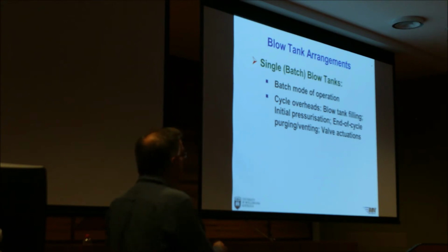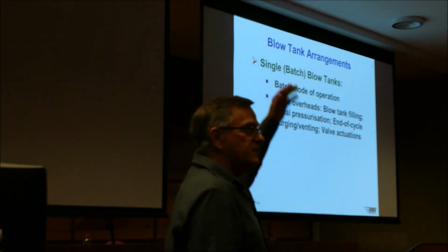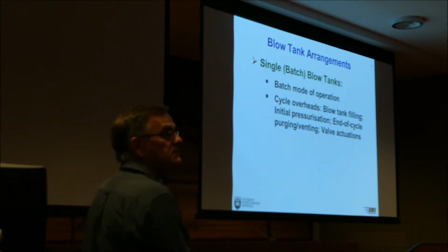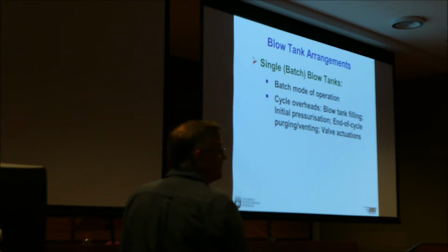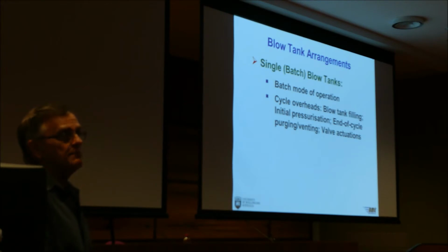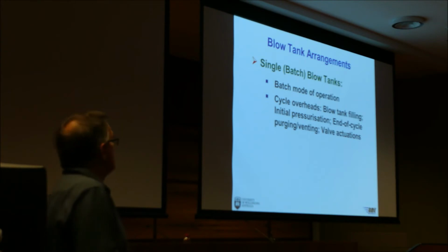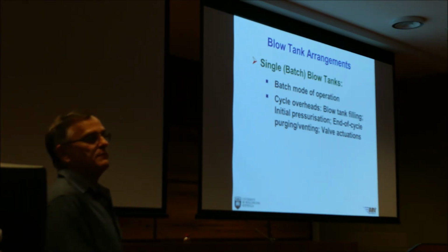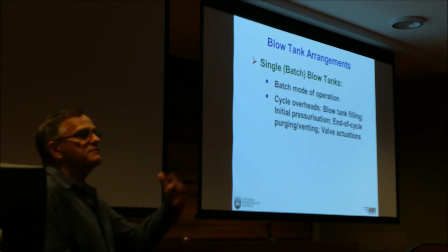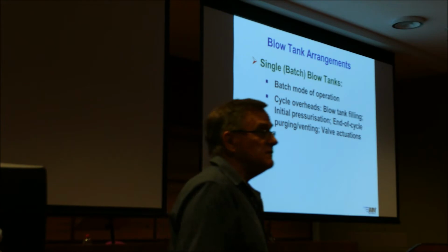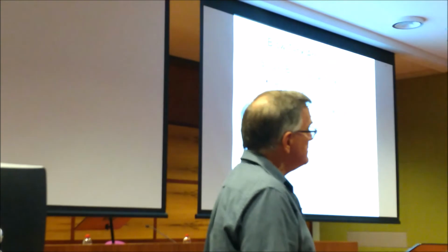So it takes time to fill your blow tank. And while we're filling the blow tank, we're not conveying anything into the bin. So you've got to fill the blow tank, you've got to pressurise, maybe, depending on your product and application. At the end of the cycle, it takes time to depressurise the system and vent your blow tank to zero pressure. Once your blow tank's back to zero pressure, you can open the inlet valve and refill your blow tank, and restart the cycle. Also, actuating your valves might take 10 seconds or 20 seconds per cycle. And that may be significant, depending on your conditions.